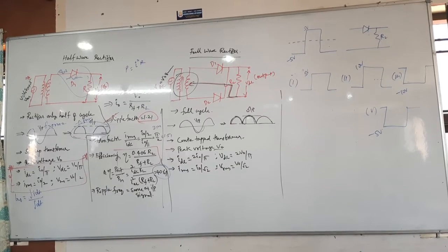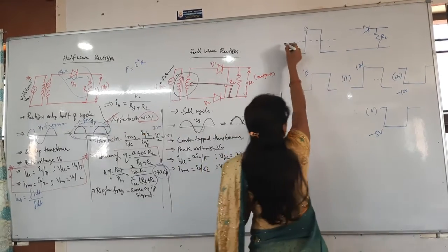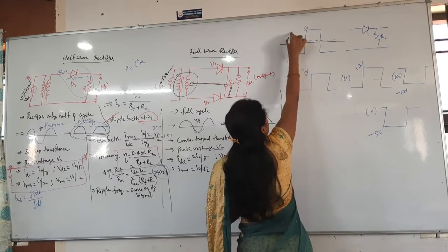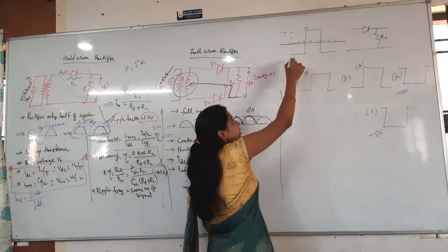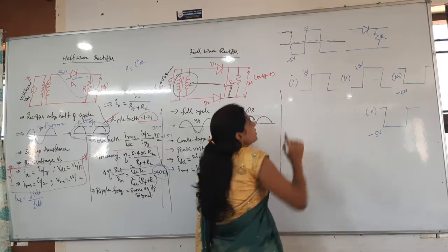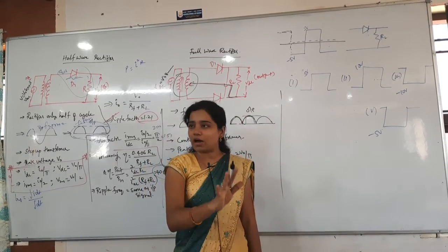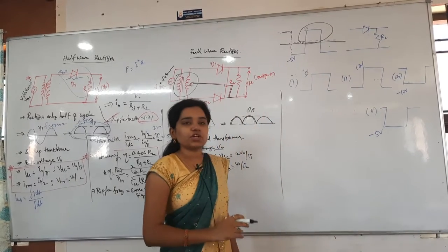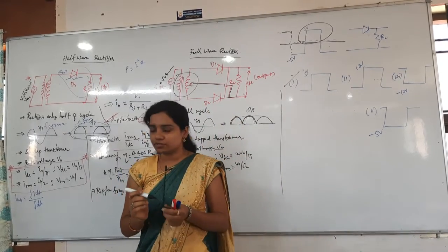It is in forward bias, so it will rectify only the positive half. This dashed line indicates the time axis here. So this is negative 5 volts and this is positive 5 volts. Now you understand the structure. Whenever I continue like this, you can understand easily. This is my signal now. So this is a half wave rectifier, it will rectify only half the signal, and this is the half signal we have taken. That's it. So which option is the correct answer? First option. That's the previous NEET question, 2015.